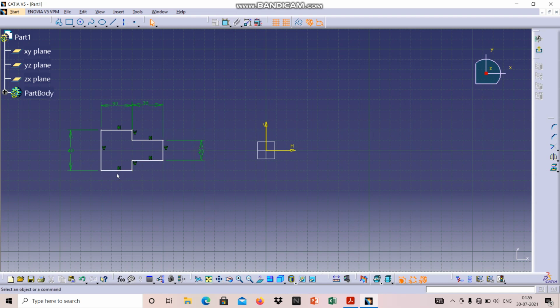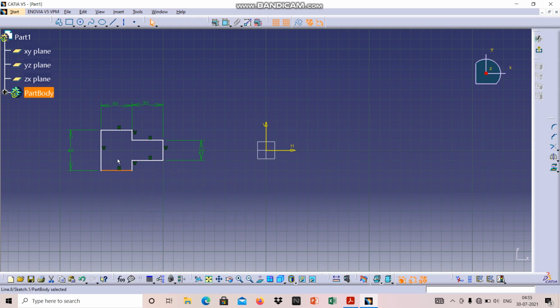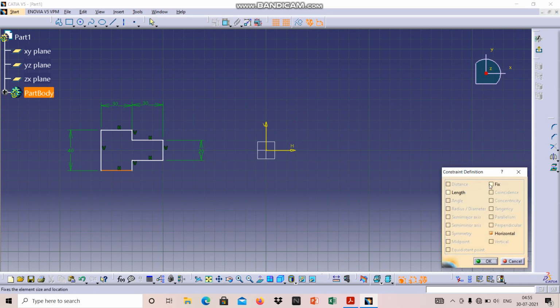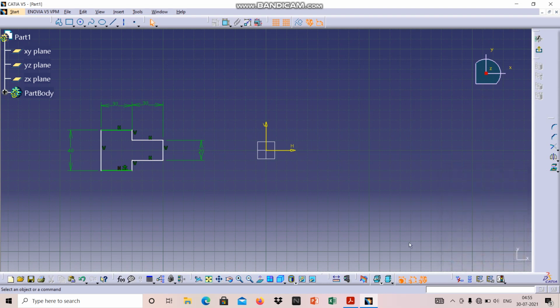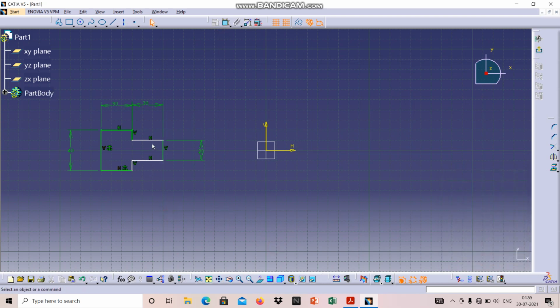And these are all the same type. So let's click here, let's add over here. Let's say we'll fix this. Right. Now if you look at the color over here, this is green. Now green color means that our sketch is fully constrained, right?